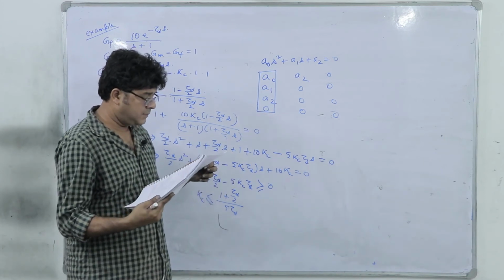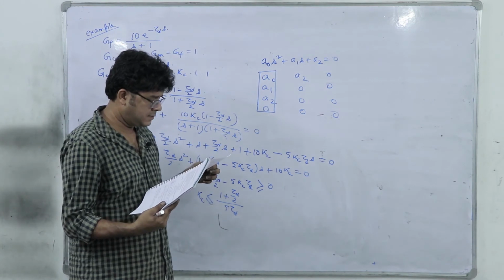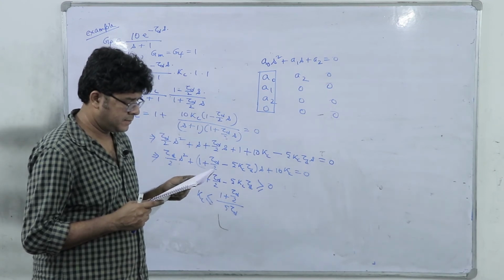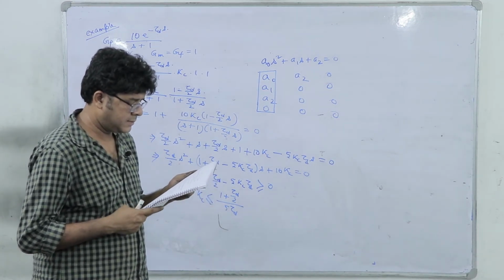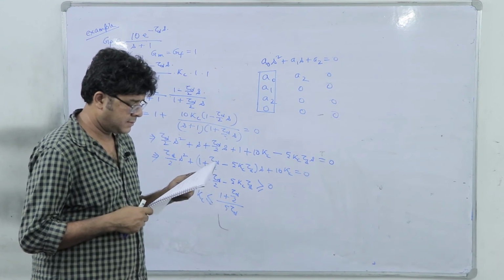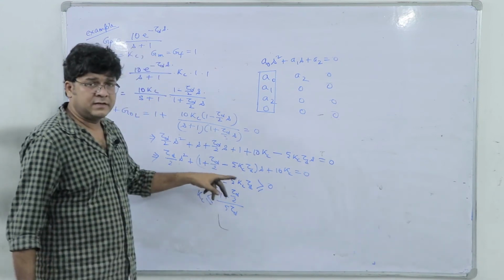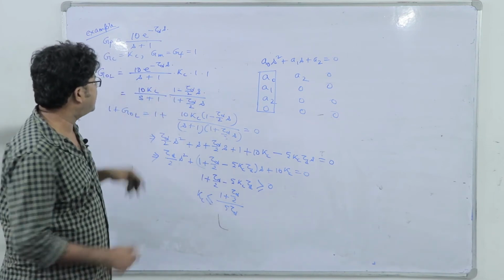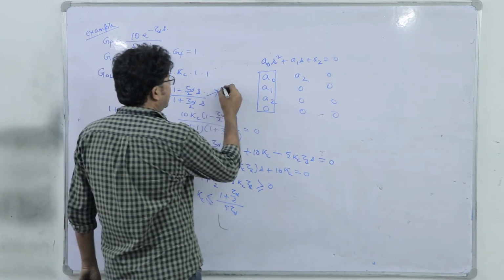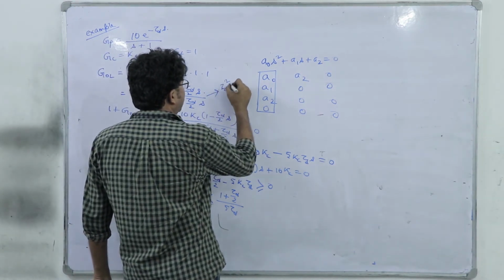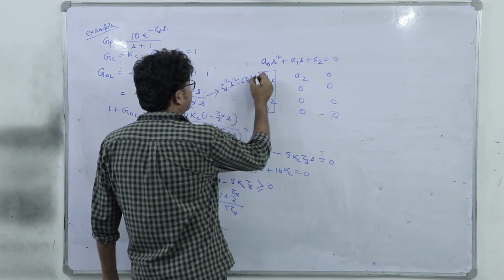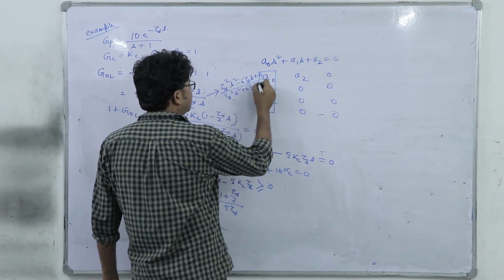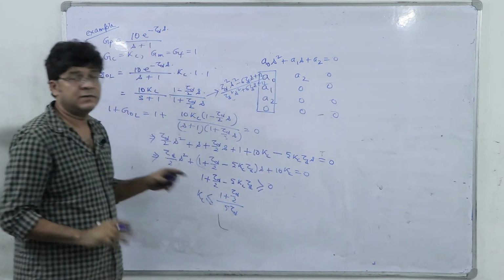So, next you see that we can check it, this is given in the example, that instead of using the Pade's first order approximation, if I use it as tau d square s square minus 6 tau d s plus 12 divided by tau d square s square plus 6 tau d s plus 12, the criterion finally will remain same.